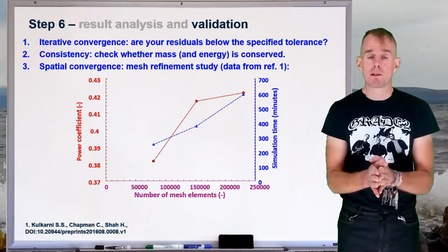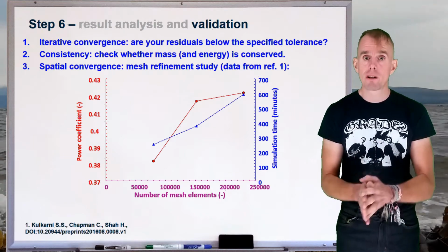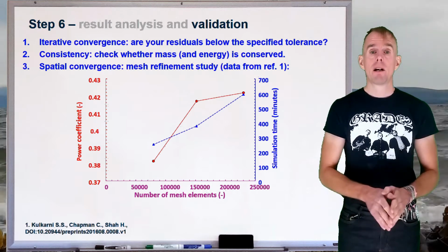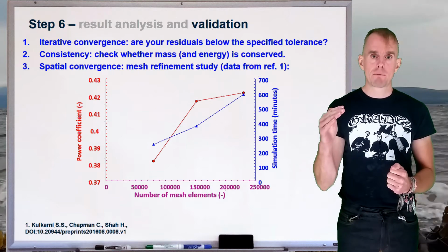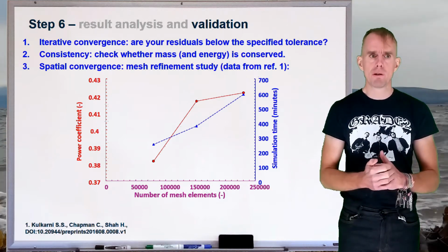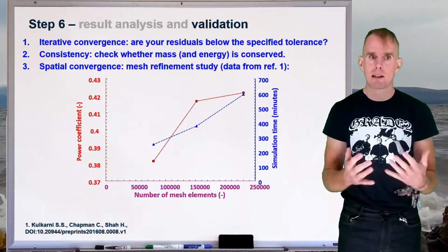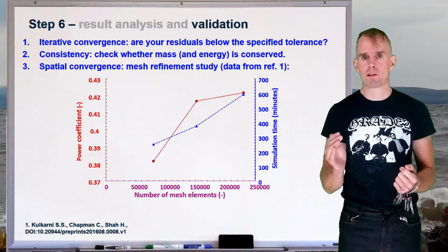And there will come a point where the mesh size that you might wish to calculate is just simply too large for the amount of physical memory that your computer system has. So, when you do a mesh refinement study, there is going to be a natural upper bound, that of the system memory within your computer. But what you should do is increase your mesh resolution as far as pragmatically possible and see how that affects certain parts of your answer.